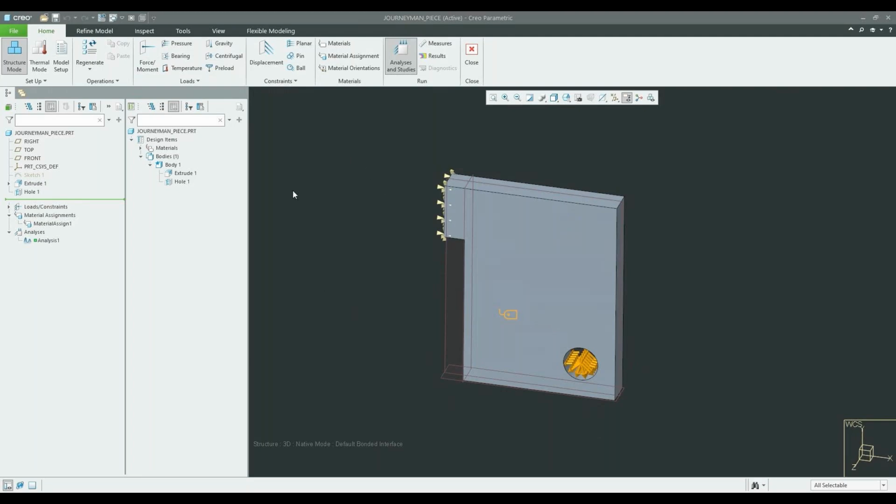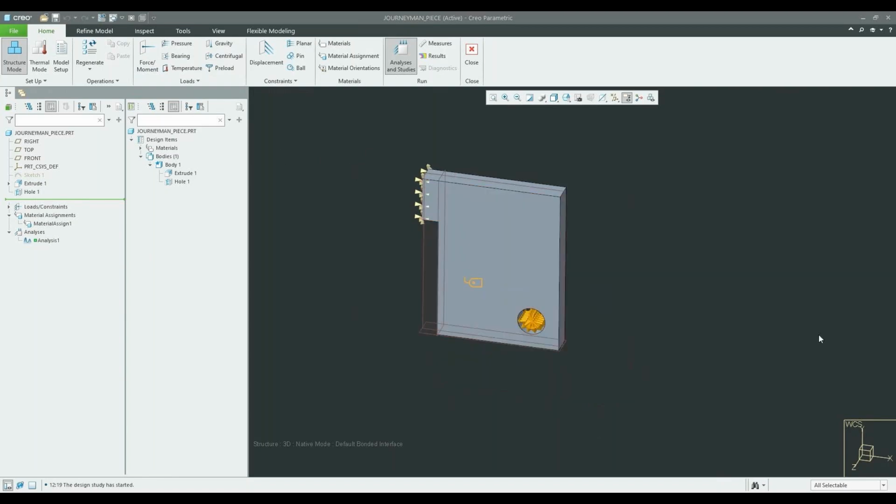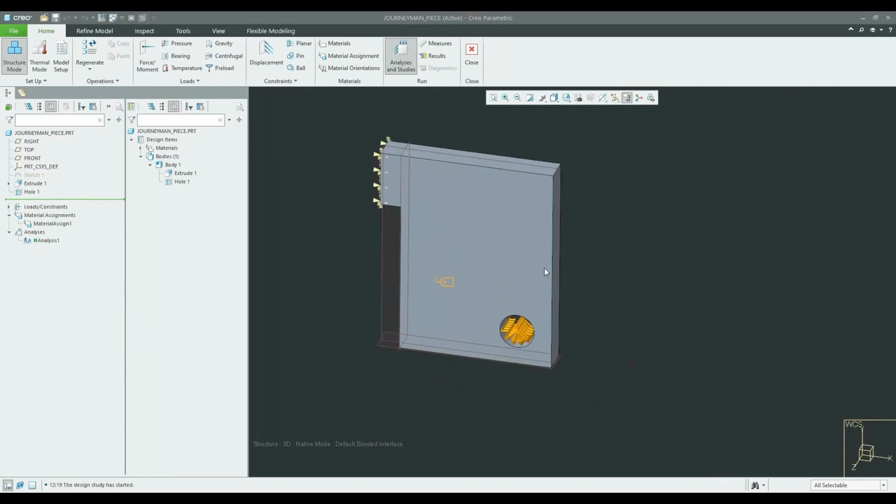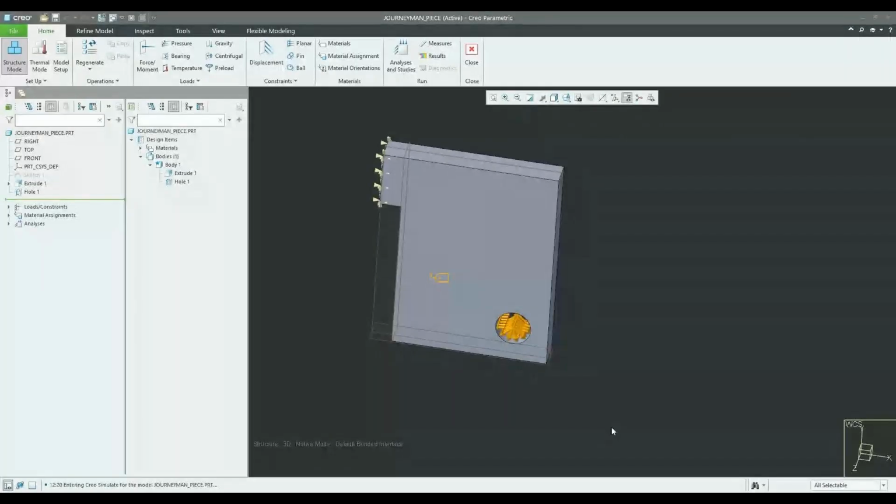So I'm going to go in here and I'm going to tell it to start this study. I'm going to overwrite the one that's there. Yes, I want error detection. And notice that happened fairly quickly. Now, I've got an analysis machine. It happens fairly quickly. It'll take a little bit of time, but I can go into the, hopefully you can see it now. So I'm going to do File, New Static. I'm going to accept everything. Say OK. So now I'm going to run that analysis.